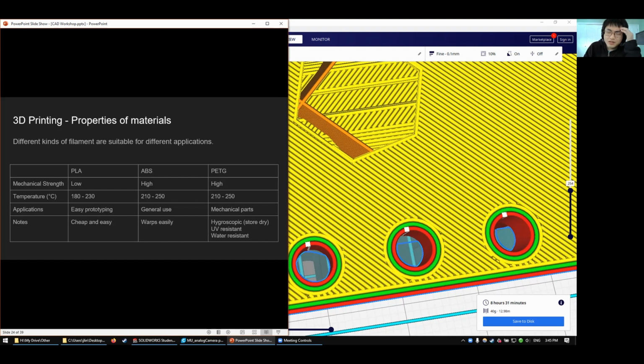When you are choosing filaments, consider not only the structure, but also the temperature you need to get it to in order to melt it. If you go with a super cheap 3D printer, it might not be able to go high enough for certain types of materials. Certain materials, like nylon and polycarbonate, are pretty high temperature, above 300-ish, I believe. Don't quote me on that. Some of them take high temperatures for the nozzles and need special superheated beds, like 90 Celsius or more. So consider the temperatures you need and also strength and other stuff.